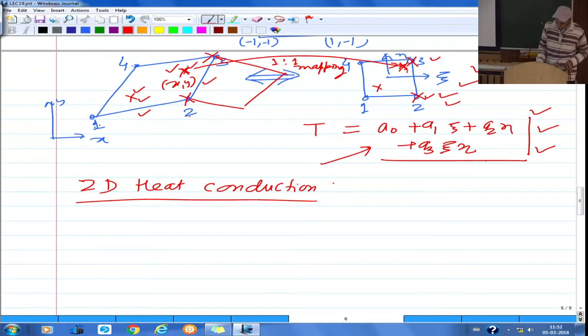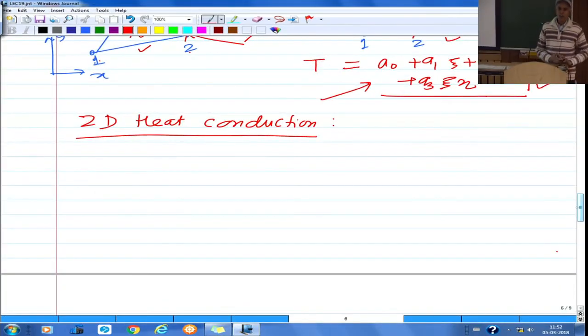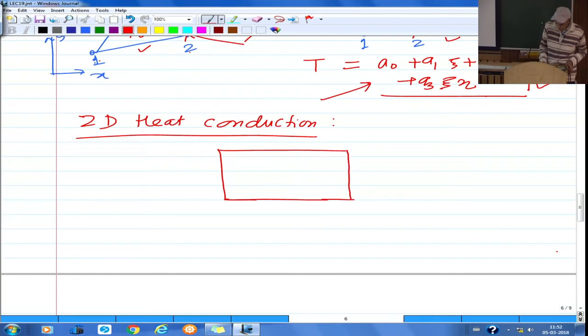So now I am going to take this example on 2D heat conduction. First, obviously, we need to look at what the governing differential equation is. Let us assume that the entire domain is a rectangular domain, with x here at one corner and this is my y, and these are the sides, this A and this B. So first we need to develop the element level governing differential equation. For that, you consider a small differential element and draw its energy input and output.